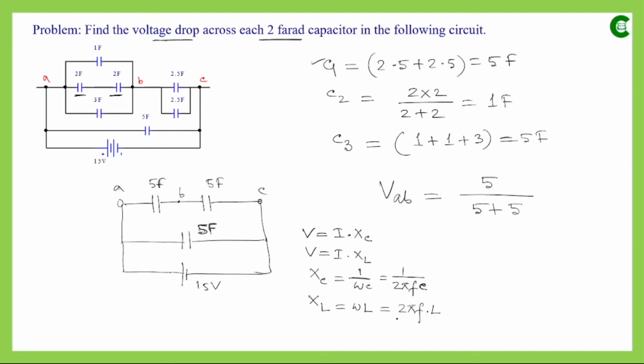But if we take the ratio of their current values or voltage values, then finally it can be expressed as the ratio of their individual capacitance and inductance values, as 2 pi f is the constant factor, because 2 pi is constant and f is the supply frequency which remains constant. So that's why in case of voltage division rule or current division rule, in case of inductor or capacitor, we can directly use their inductance or capacitance value in the ratio, likewise we use in case of resistive circuit.